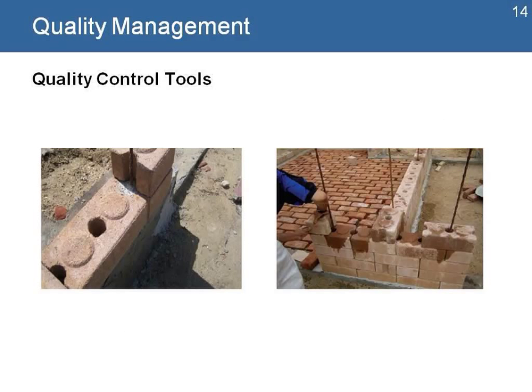Here's our example, where we look at the construction of bricks for houses. You might need to produce millions of bricks, but every 100 or 1,000 bricks you test one for durability and strength, to make sure it has the correct mix of materials, because those bricks are going to be used in the walls and will be part of the structural foundation and the stability of the house. And if something is wrong with a group of them, then you might have problems with that house when it's under a lot of stress or weight, because they might increase the risk to the people and families living in those houses.